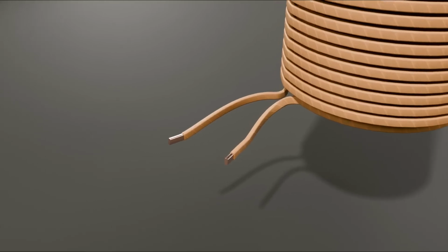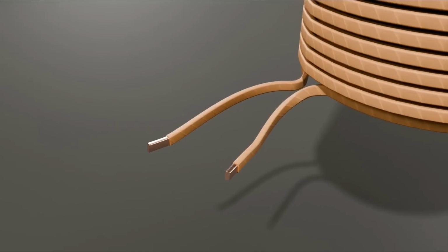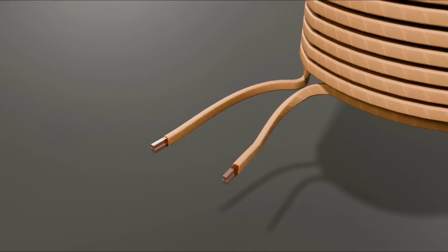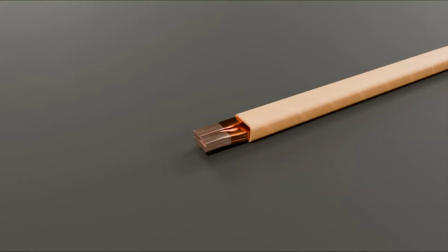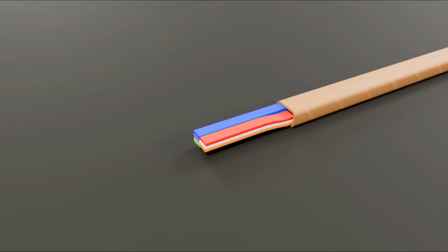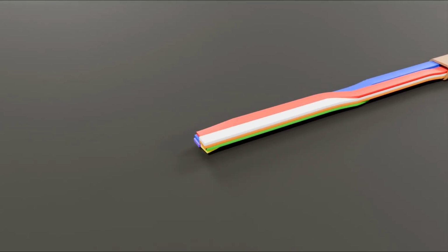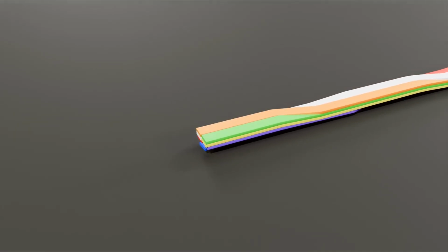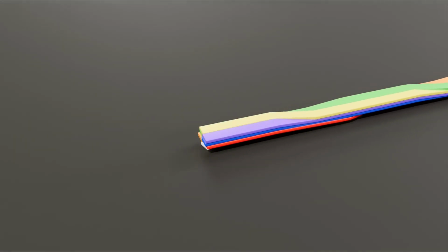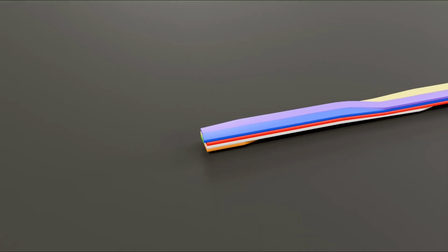However, using a single solid conductor can cause eddy current losses. To mitigate this, a continuously transposed conductor is used in a low-voltage winding instead of a single solid conductor. A CTC consists of multiple strands, each insulated from the others by varnish coating. In a CTC, the position of each strand continuously changes along the length of the cable. This prevents circulating currents caused by differences in the induced voltage of each strand.